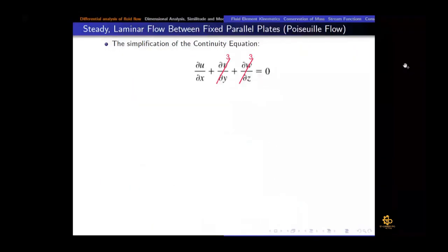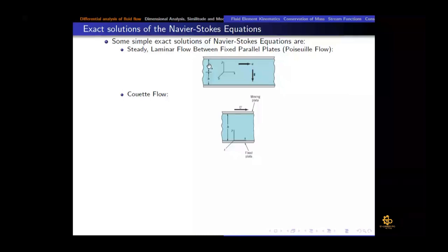So we discussed the derivation for the velocity profile and then the volume flow rate for the steady laminar flow between fixed parallel plates, when both plates were stationary. It means that both plates had zero velocity. But there is another type of flow which is called Couette flow, in which the lower plate has zero velocity and the upper plate has some finite velocity. Usually this type of flow occurs in a ball bearing, because we know that it is a circular object.